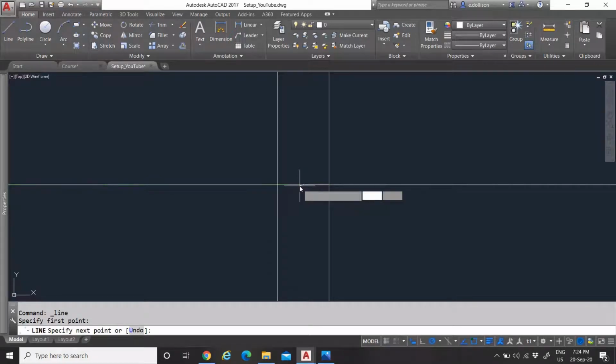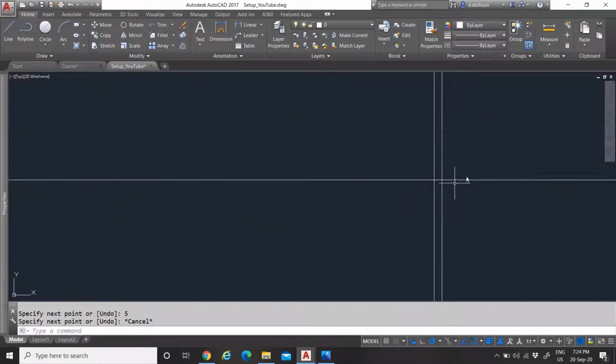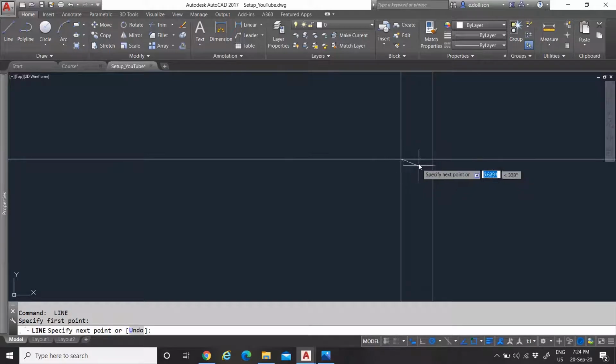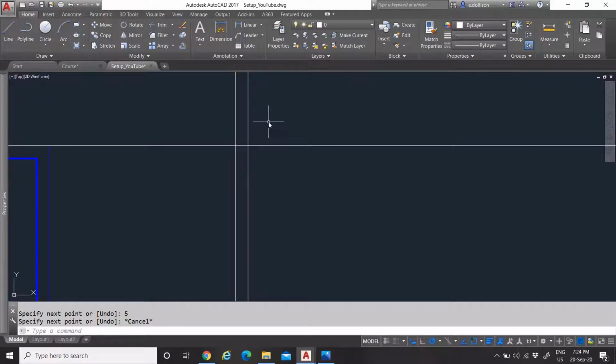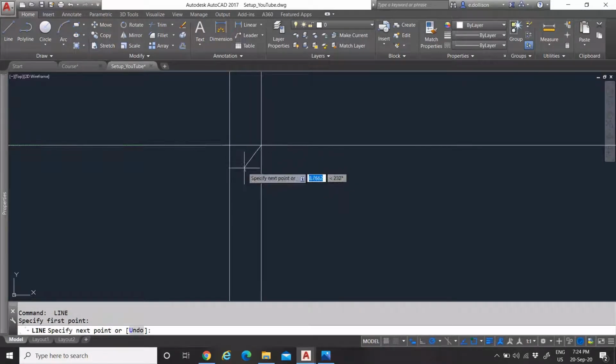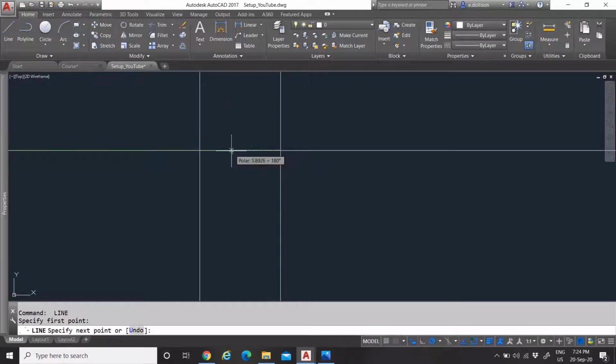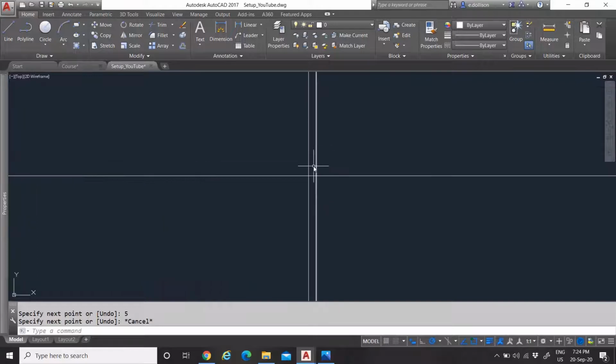this one is going to be 5 millimeters that way, 5 millimeters this way. Enter. When you press space after you have drawn a line, AutoCAD will remember what was your last command. So when you press space, it will go back to drawing a line. So all you gotta do is press space, and then it will automatically go to the last command that you already had. So here, 5 millimeters, enter, escape, and then space.